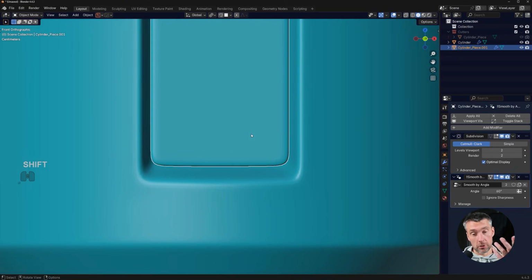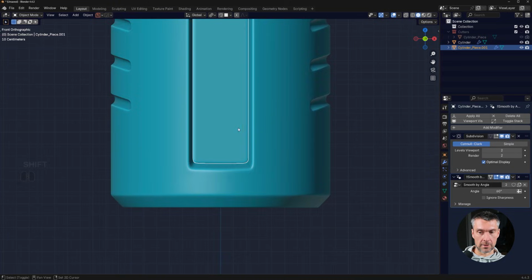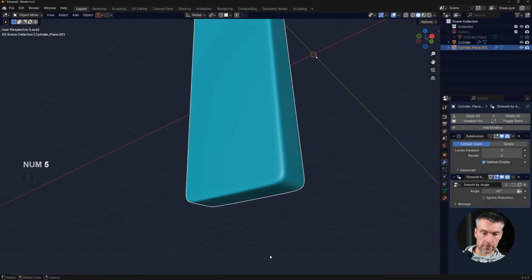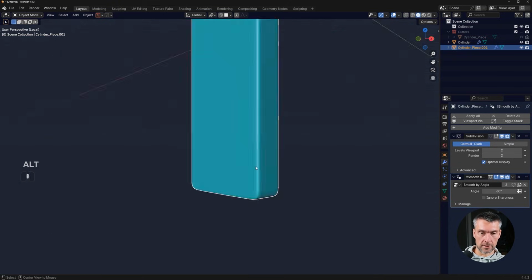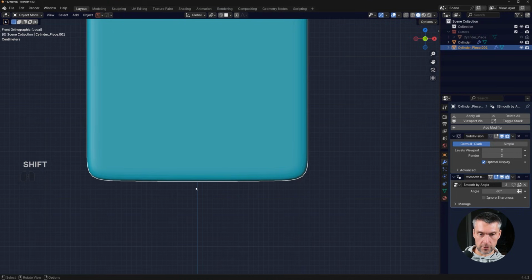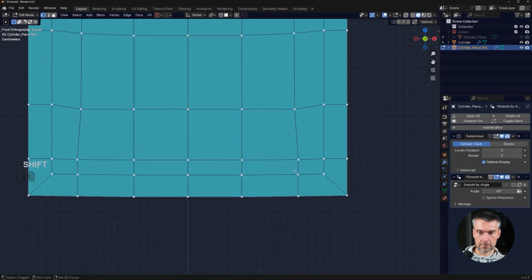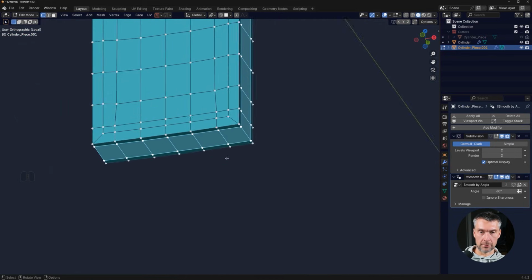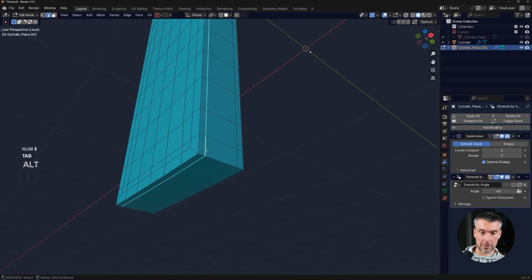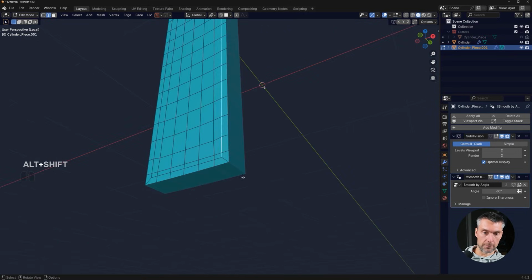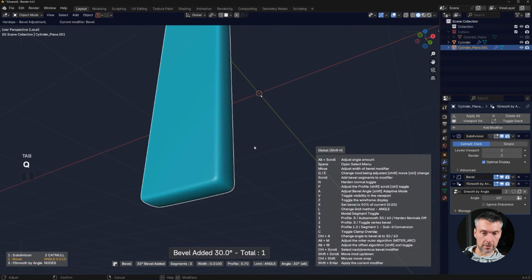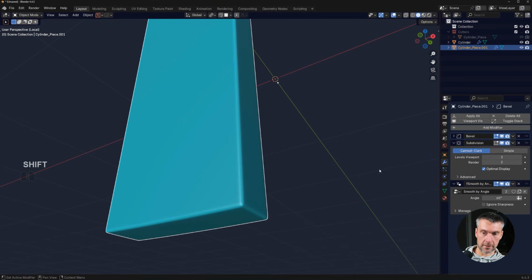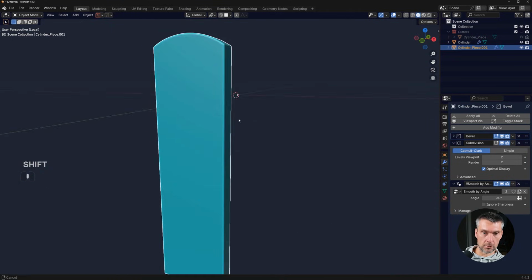Now, honestly, personally, I would prefer to run a bevel on this instead of running a subdivision bevel, because it's going to be much easier to run a boolean on this. And I'll show you what I mean. So you see, we have this curving here going up, right? And that's because this corner is really relaxed here, so we will need to tighten it up and play with subdivision and all that, so it's a bit annoying. So what I would suggest doing instead, I would remove these, right? Then I would run a bevel on it above the subdivision, which is going to hold it, okay? You see that? It's holding this whole structure.